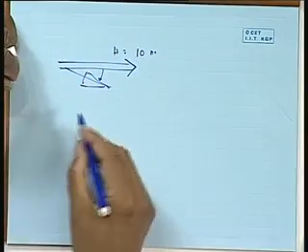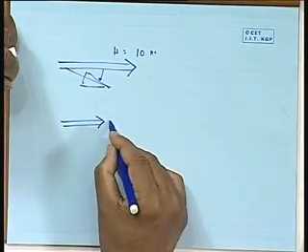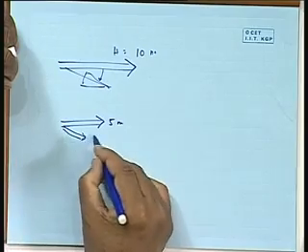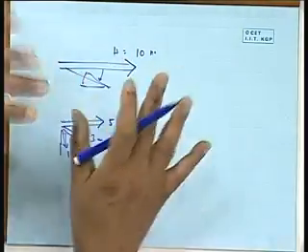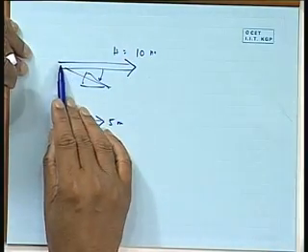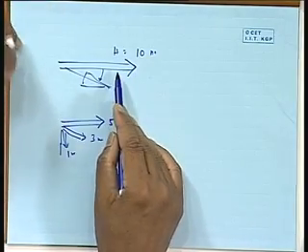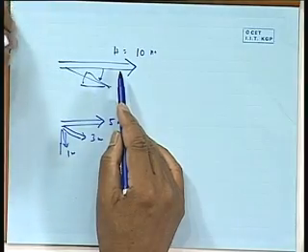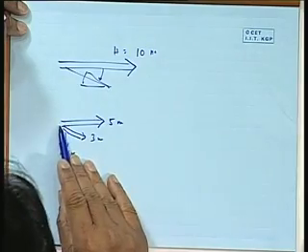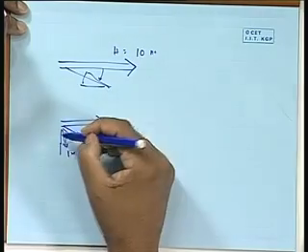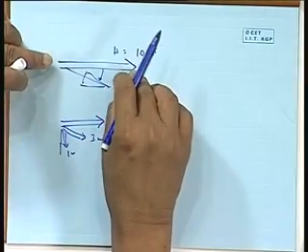But now what happened, I am trying to say that this 10 meter energy is not all 10 meter. There is actually as if a wave coming of 5 meter here, a wave of 3 meter here, a wave of 1 meter here, like that. As if the wave energy is spread. The wave that is coming in this direction of 10 meter, I assumed it is not so. What is happening is that there is a total energy equivalent to a 10 meter high wave, but the direction of the wave is spread. That means that energy is spread due to a wave of 5 meter height this side, due to another wave of 3 meter height this side, due to another wave of 1 meter height this side, etc. So that when you sum them together, the energy becomes the same as the energy of the 10 meter wave.